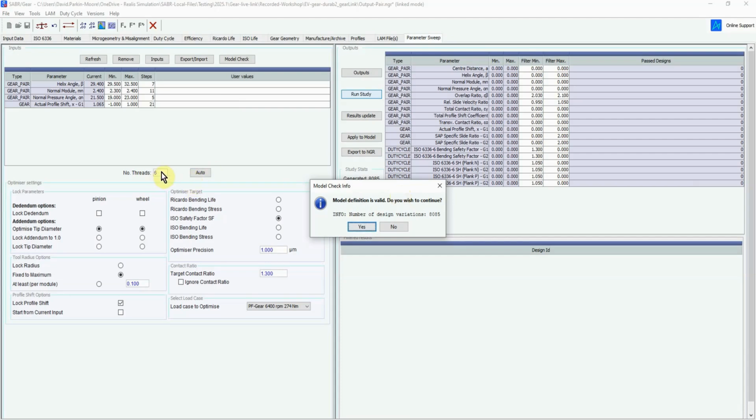The default number of threads is the number of threads you have on your machine minus 2. So if you have many more than 8 CPUs, which is all I have, then you can increase this number. It will increase it automatically, and the runs will be a lot faster. So I will run that, and then we will have a look at results in the next video.